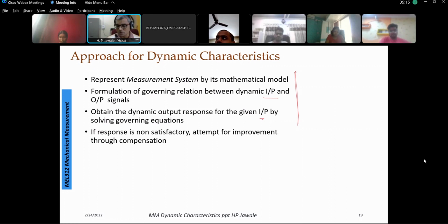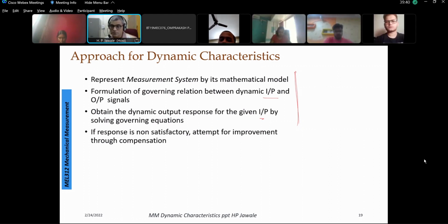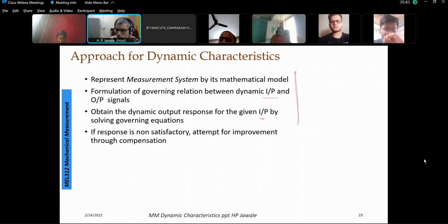What if the response of the system is not as per the desired? I'll give an example here. Suppose we are designing a system for measurement of pressure under dynamic condition, and we know the maximum pressure that the system can have. Say, again, the IC engine chamber: the maximum pressure that can be generated is anticipated by our governing equation of the phenomena. Then we know that in a small fraction of time we are going to have large variation in the pressure, and we want to capture those. So the boundary limits within which the measurement instrument has to perform are known.